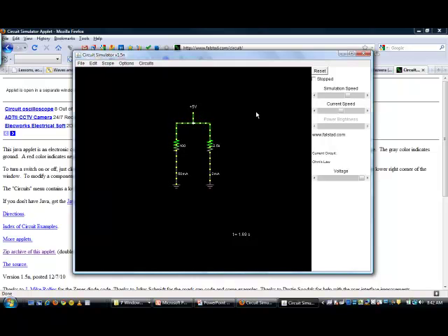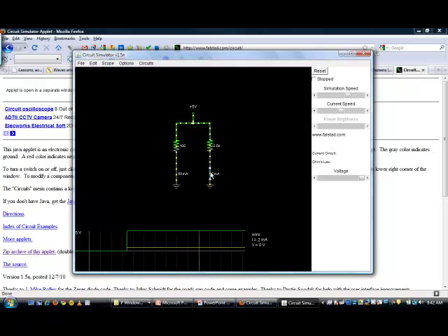Okay, now one last thing with this pre-made circuit. You notice that we can change it, but we can also view the voltage across one component as a scope, like here. So in this particular case, we see the voltage in green as a function of time. And the voltage drop across it is between 5 volts here and 0, so it's 5 volts, so it is a constant green line. Now the yellow line is the current.